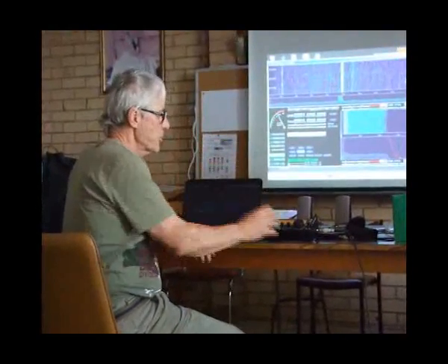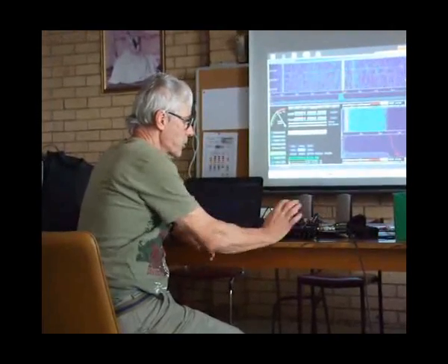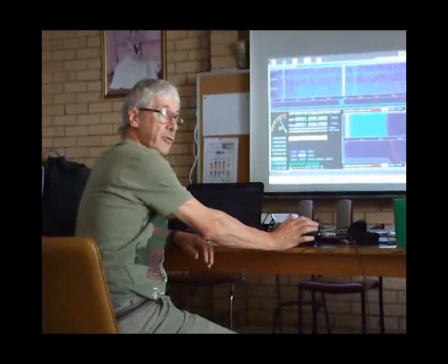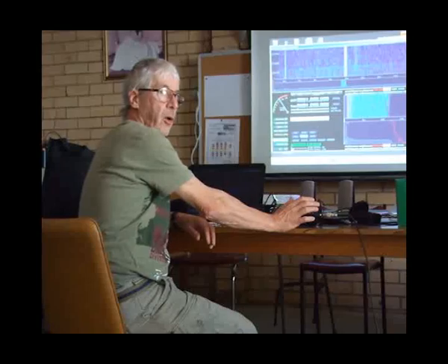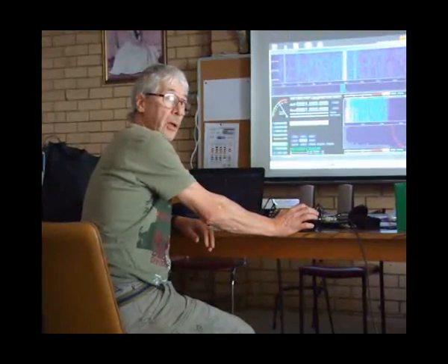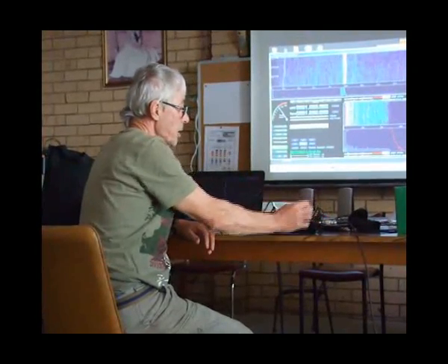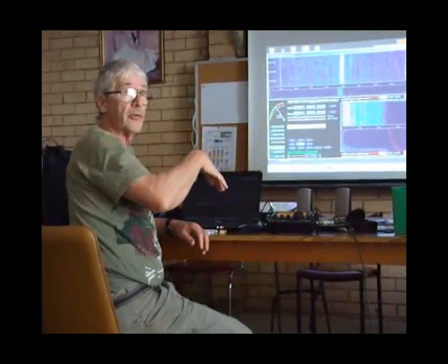Another thing too is that you can set up the main knob and the second knob in two different ways. You can have the main knob as VFO-A and VFO-B. You can tune separately on the small knob, but you can just press that knob in and change its function, and you can make it into a fast tune knob, so you can rip through the band in whatever step size you want to select.